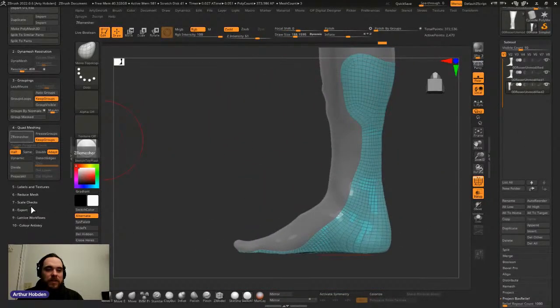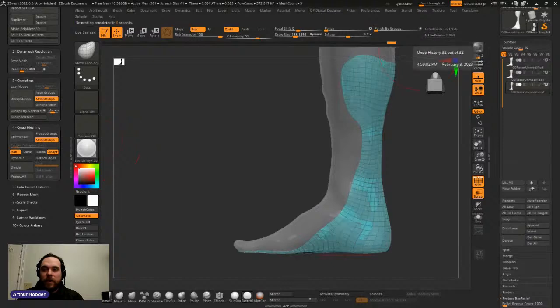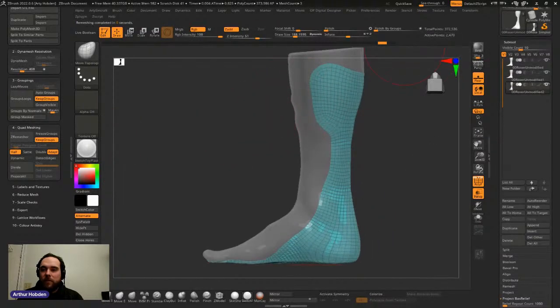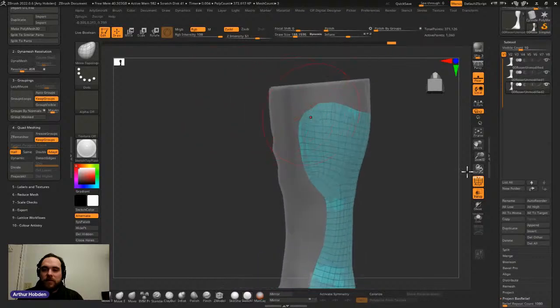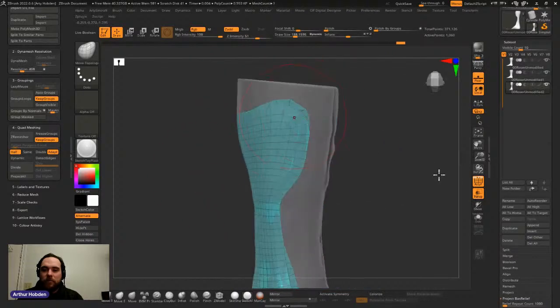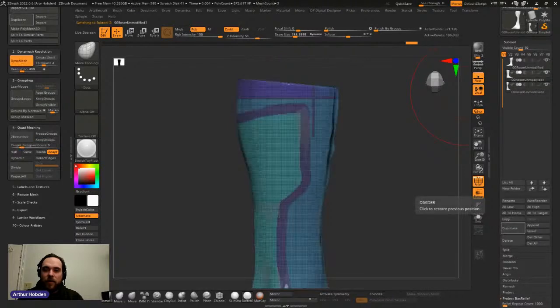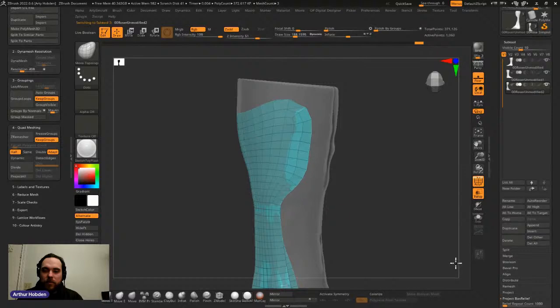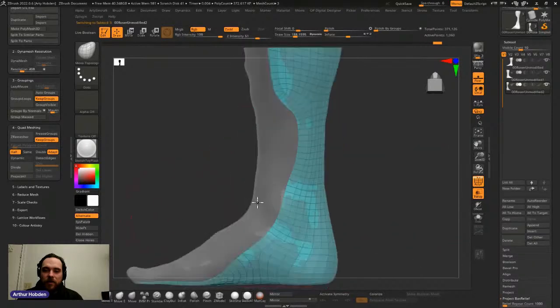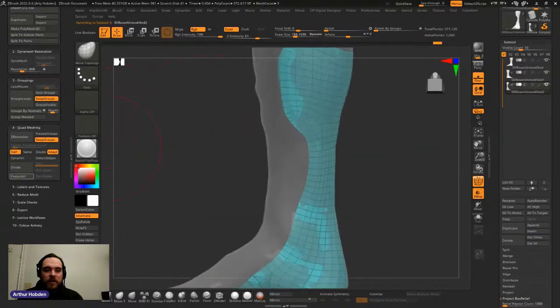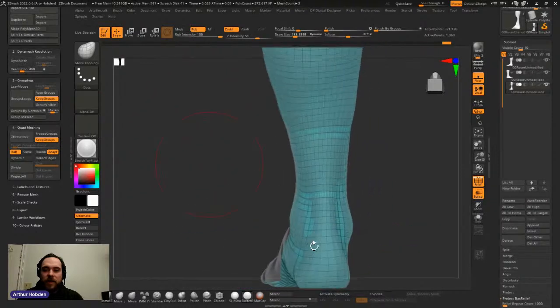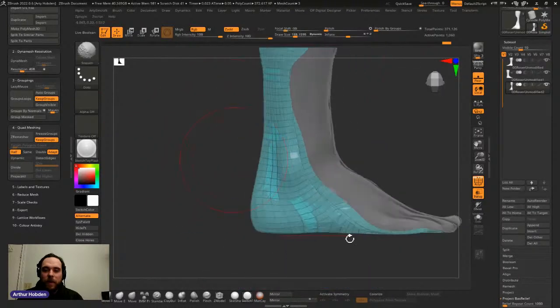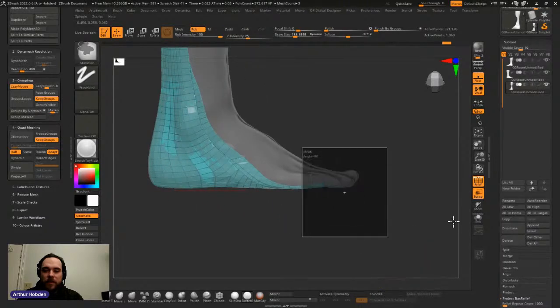Let's now remesh this at half strength again. So look what we're getting at. We're getting at 1,000 points. We're losing a bit of our trim line, just a bit. I mean, not bad. It's not terrible. We're going to have to re-pull up that corner a bit. That might be something we have to account for. Bring that up so it's next to where our original is. If I turn on the original, we can kind of see where that's coming through. We might want a corner here. Go to the other side, bring up that corner, and we can project again just to bring it all back. This is very accurate, nice and smooth quad meshing. Let's now focus on the foot plate and clean up that foot plate.